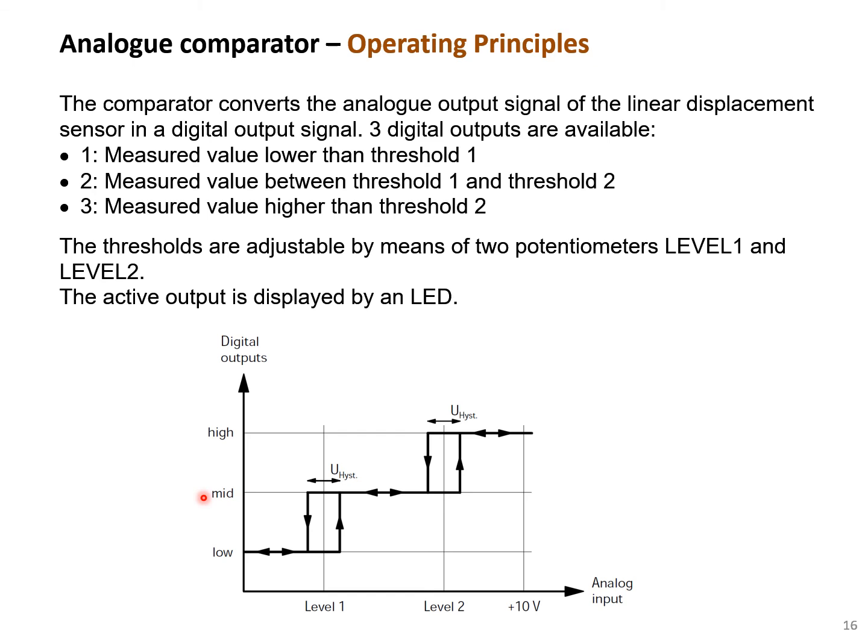output 0. And if the thickness of the object is less than level 1 or more than level 2, it means that it's not a normal object, it is off from the standard, and that should be rejected. So we could adjust that comparator to have output 1 in these cases. So for both cases, the sensor output will be true.